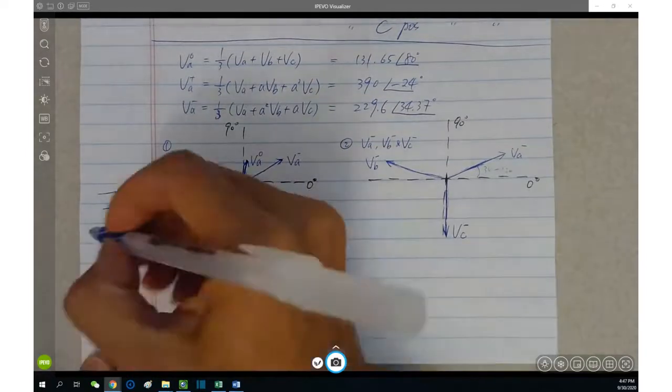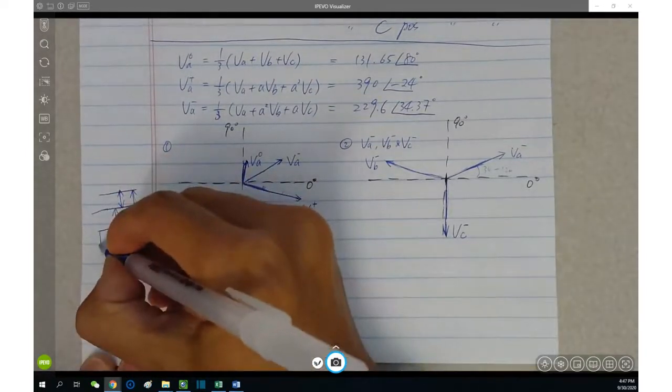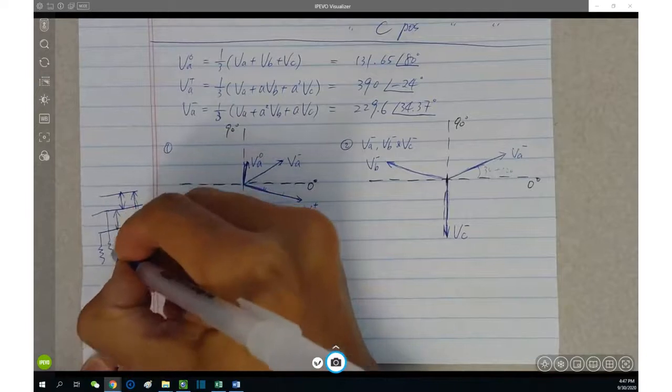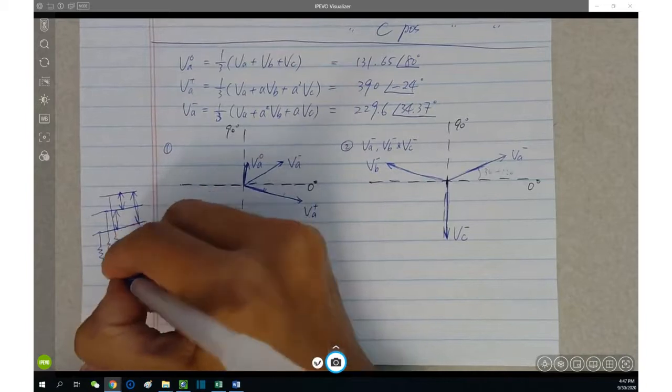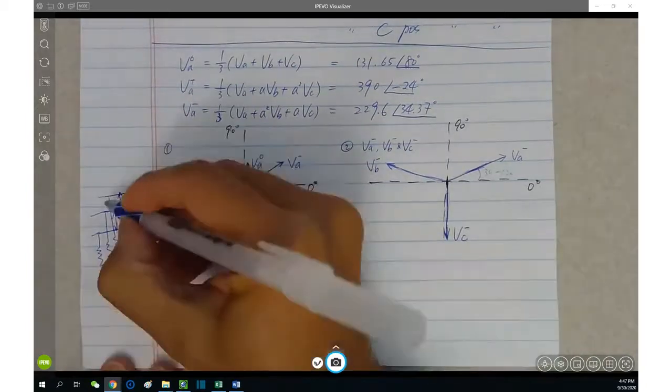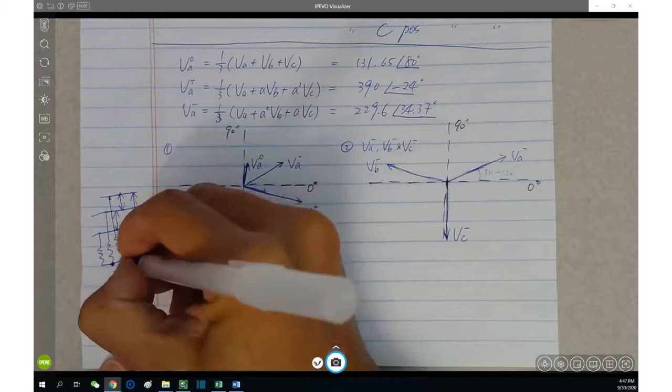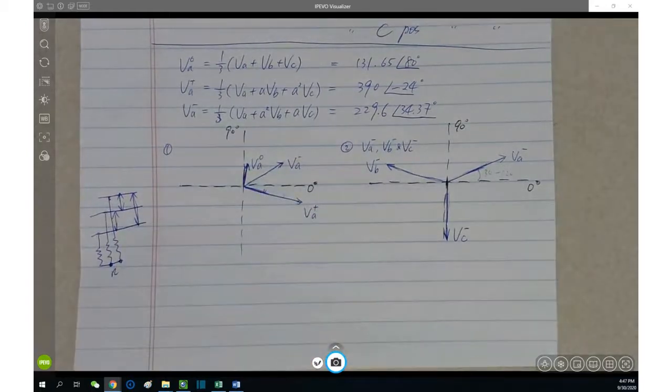So what I did is like this. I used a big resistance, also balanced, these three balanced, to create a neutral point here. And then I measure from here to here as the phase voltage. This is what I did. Okay, that's a pretty cool idea. Yeah, and that's actually also practical. I learned this from my advisor. I wasn't that smart to create this; I was taught.